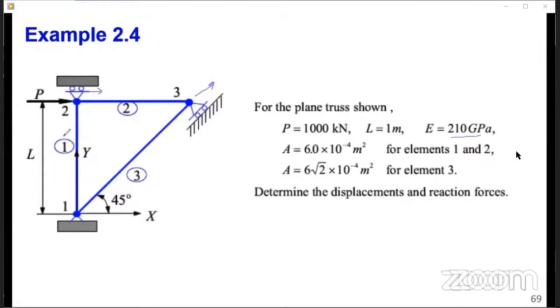Remember, another thing you have to notice is that for this example, we already have discretized our structure. So that's why you see the nodes are defined for you, the elements are indicated. But if you were told to solve this using the matrix method of structures, which is the same as the finite element method, you don't have to have these elements shown or indicated.